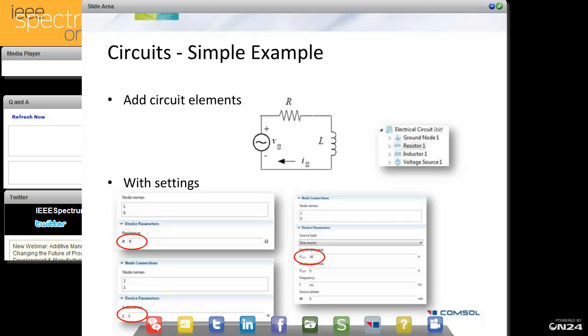Adding circuits to a model is of course of interest, and that's easy to do in COMSOL Multiphysics. And there are special coupling elements, so there is a special type of circuit element you can insert in the circuit that represents the finite element model. Apart from that, it's pretty straightforward, typical SPICE standard implementation, where you specify the pins of each component, and that's very much it.